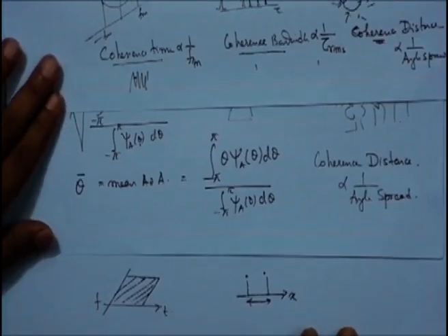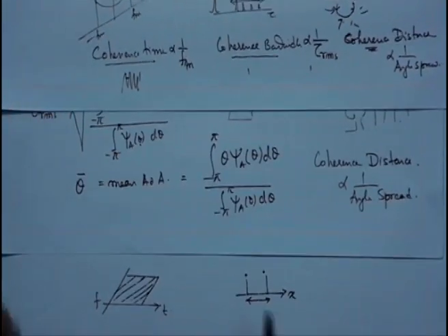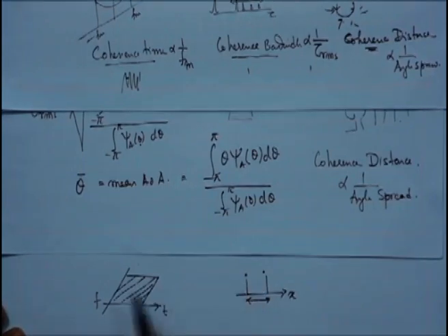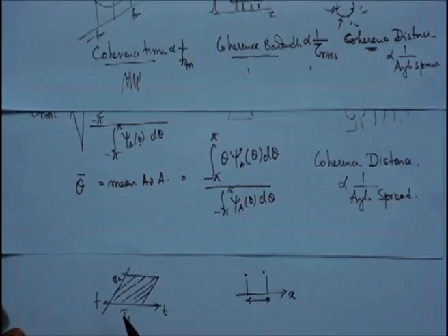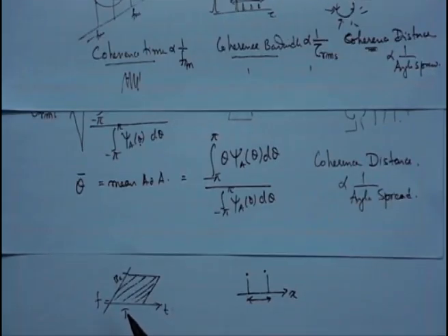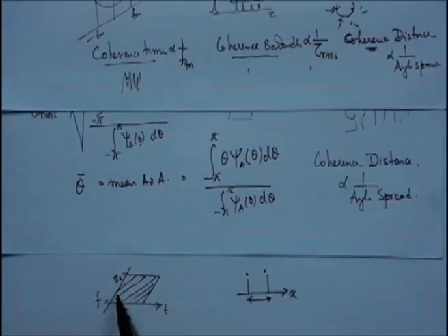Here we would have loved to have a longer coherence time and a longer coherence bandwidth because we could do with easy equalization. Of course, there are problems, because once the signal is in a certain state because of the channel, the channel won't come out of that state very fast if the coherence time is long or if the coherence bandwidth is very large.